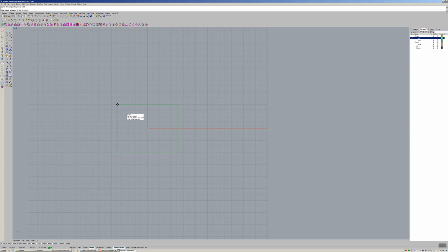Okay, so we said 2 inches is about 50 millimeters. We're going to type in 50, enter, 50, enter. And now we have a 50 by 50 square curve reference. So now I know exactly what's 2 inches. It's 50 millimeters to perfection. So when you 3D print, you should get 50 millimeters from your 3D printing. There are some tolerances, but we'll get into that later.